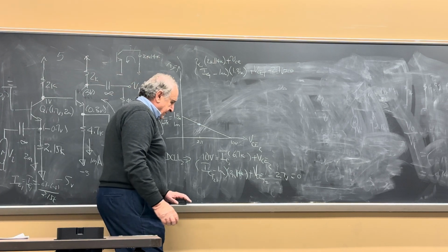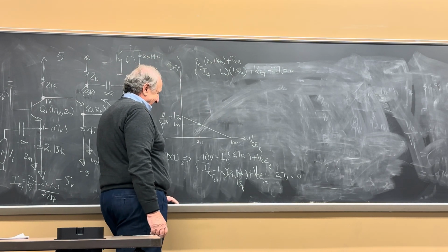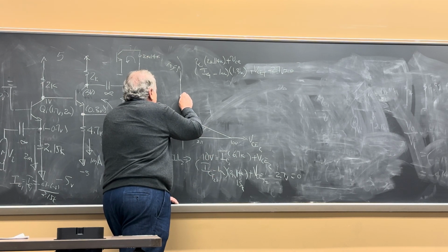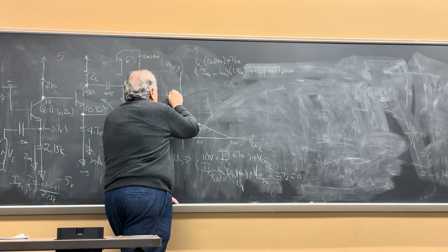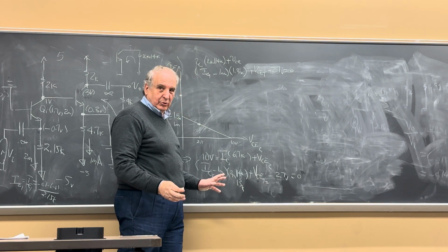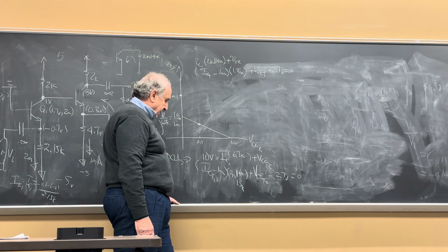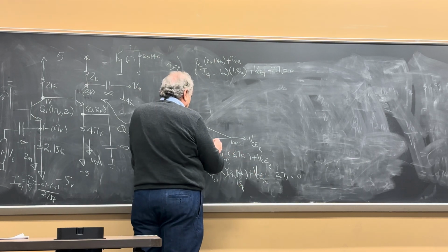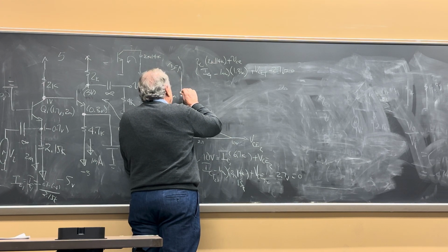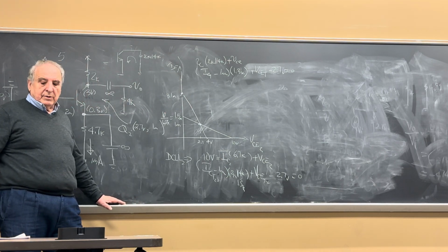You plot this. This is 1.3. You get this intercept approximately 3.1 by setting this to 0. 2.7 divided by 1.3, approximately 2.1 plus 1, 3.1. And this would be 1.3 plus 2.74. So it goes like this. This is 4 volt. That's your Q, the DC load line.